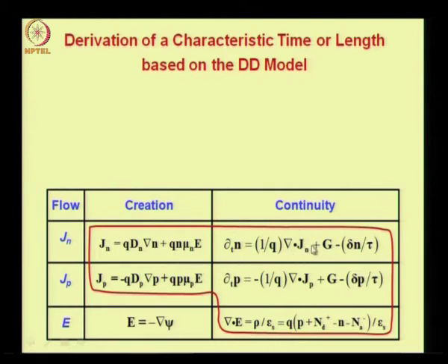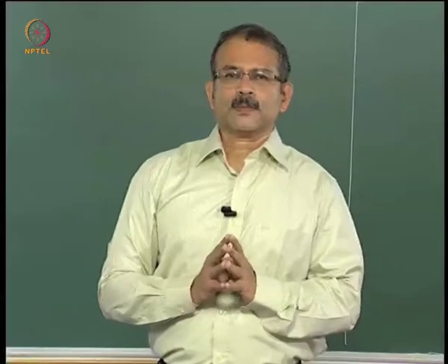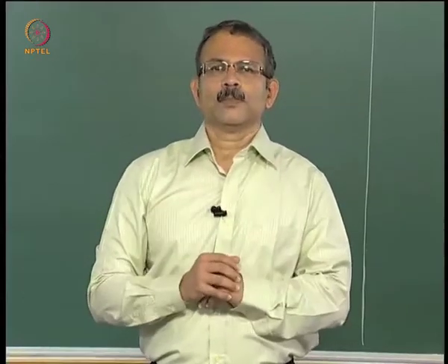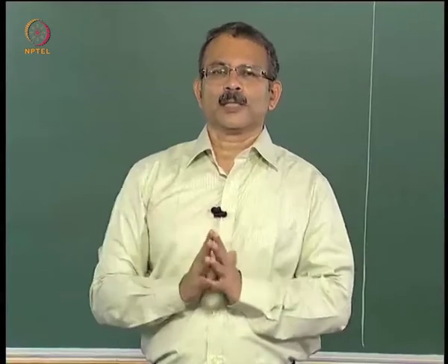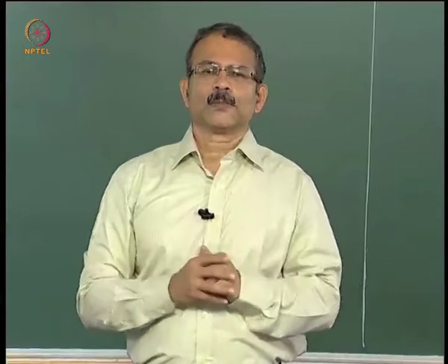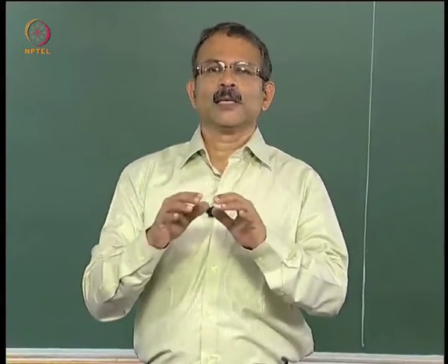because when you take a divergence of Jn, actually you will have to differentiate each of these terms with respect to x, and further the diffusion coefficient and mobility will have to be assumed to be constant, otherwise each of the terms will have to be differentiated according to the product rule and you will get many terms in the equations. So this 3 coupled equation form is suitable for numerical simulation but not for analysis. For analytical approach one uses the equations separately.